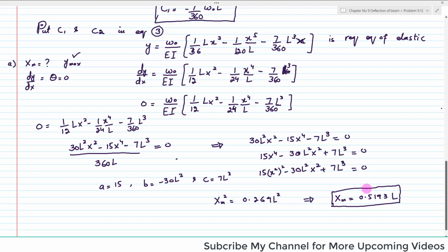Clear? Now we will put this in the equation of elastic curve. So when you put x is equal to 0.5193 L, you will get the maximum deflection.